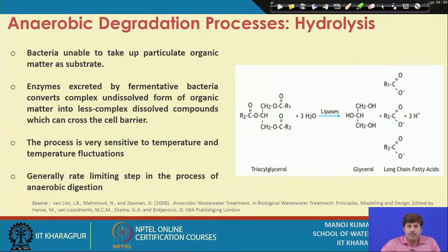Now, if we see the hydrolysis step, why does the hydrolysis take place? It is basically because bacteria are unable to take up the particulate organic matter as a substrate. There are few species which can take that up, but they are very few in numbers, and in general bacteria cannot take up particulate organic matter, or the organic matter which is in the solid form, which is not solubilized or not dissolved in the water, as their source of substrate.